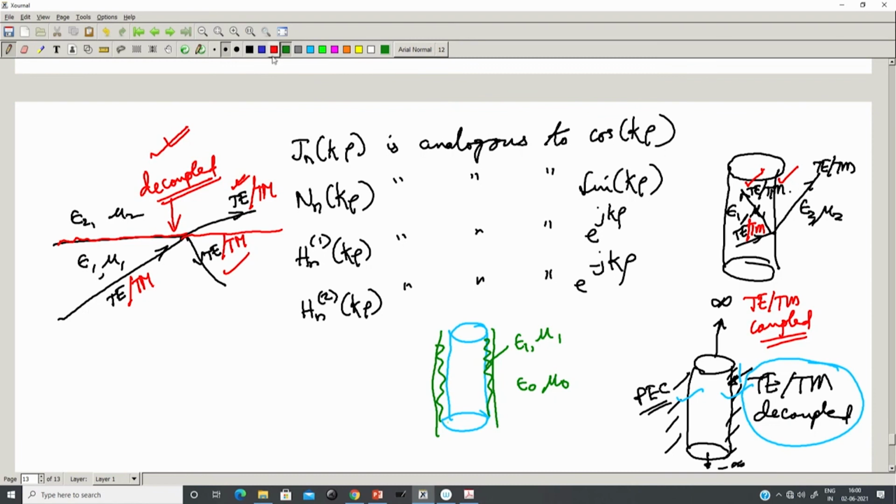So, this will be a very practical problem if I want to have, for instance, a conformal patch here fed by a coaxial probe from here. The inner conductor of the coaxial probe will be touching the patch through a hole and the outer conductor will be shorted to this ground plane. These situations are going to arise in the design and rigorous analysis of all kinds of conformal antennas on cylindrical surfaces, where rigorous mode coupling has to be considered at the dielectric regions, otherwise your analysis is going to be extremely inaccurate. It cannot describe the wave behavior in these regions. So, this is important. However, we are not going to go to such advanced treatments; we will be limited in our analysis to the circular waveguide.